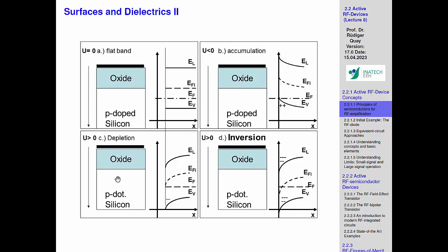But it's something that you push one carrier away and you get, just out of nothing, carriers of the opposite type. And this is just a law which directly derives from the distribution laws. It is the basic law when you make assumptions about what happens in a crystal, and you learn that specifically this intrinsic concentration is a constant, and this is related to the n and p doping, or the carriers which you have available.